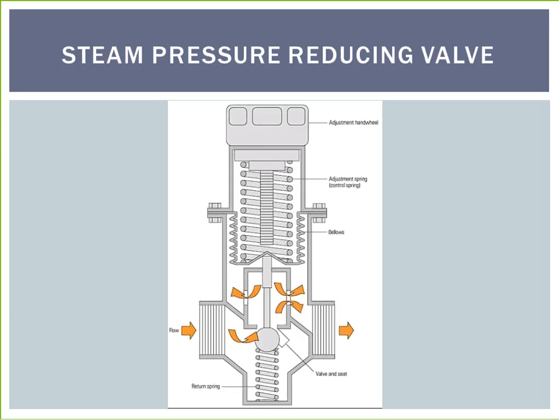They automatically adjust the amount of valve opening to allow the pressure to remain unchanged even when the flow rate fluctuates. While it is possible to maintain a constant pressure by using the combination of an actuated control valve, a pressure sensor, and a controller, a pressure-reducing valve offers the advantage of being able to control pressure through fully automatic, self-contained operation, requiring no external power source.